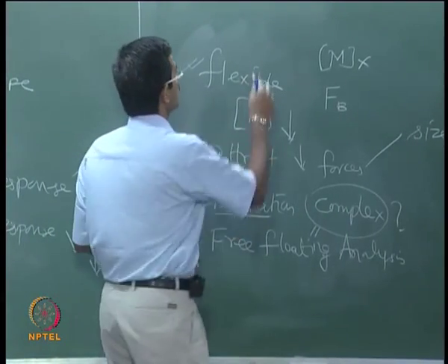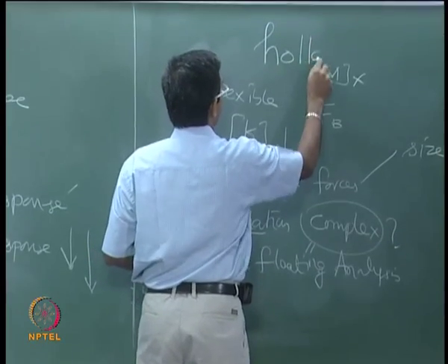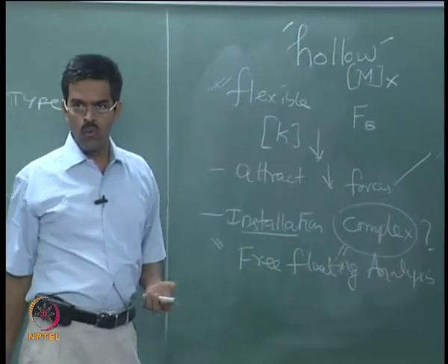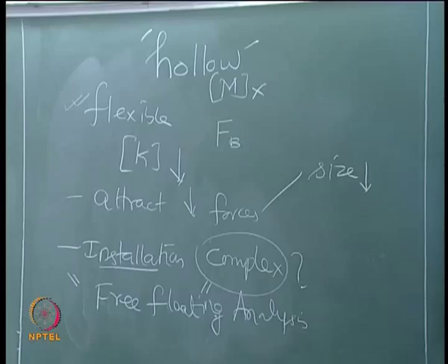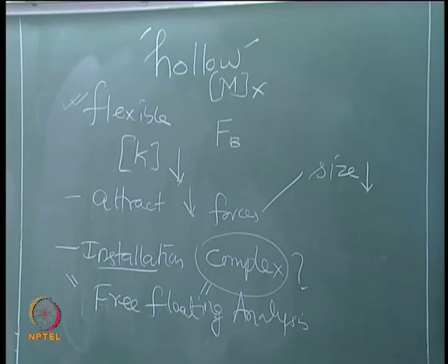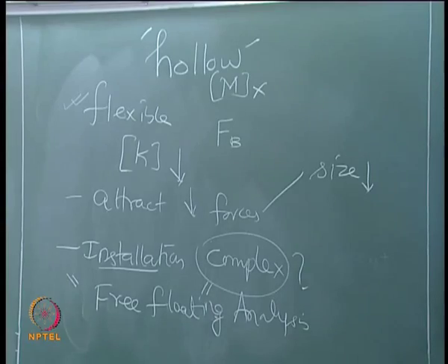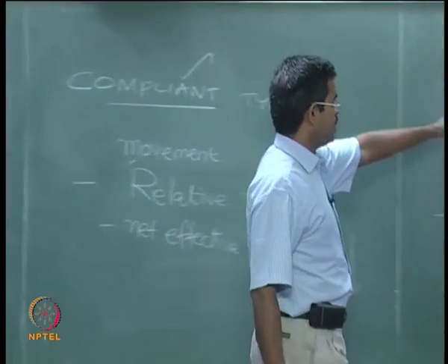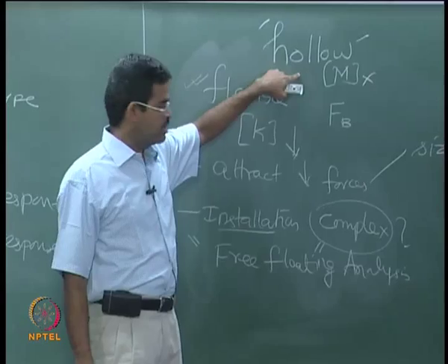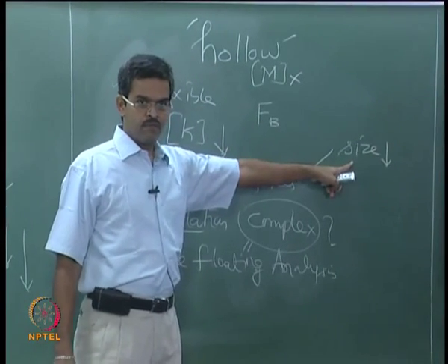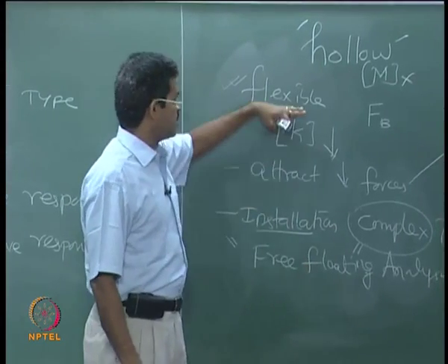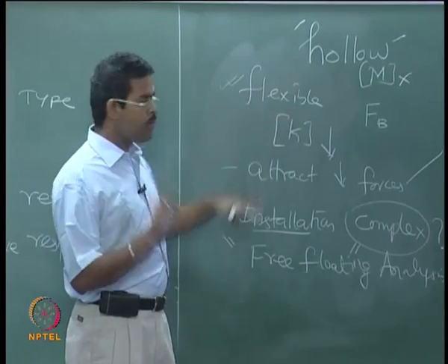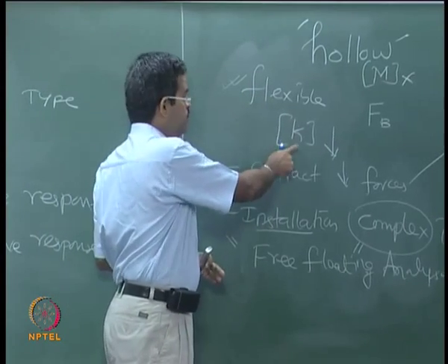Therefore, we can talk about hollow or void cylinders, what we call as pontoons. So, this is how this platform evolved in geometrical design, that instead of having solid structures, go for void based elements, so that size can remain the same and weight can come down. Because of the flotation characteristics, the structure can become flexible. The moment the structure becomes flexible, stiffness is reduced.